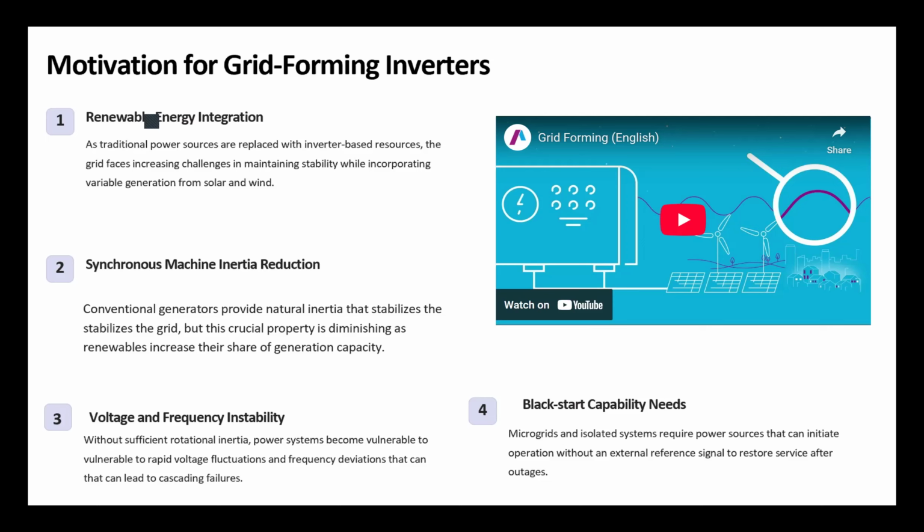Okay, we are going to need time for transitioning from one state to another when we have a mechanical system. On the other hand, in inverters, we don't have that delay. When you change the setting of the inverter's control system, the output changes instantly. So any kind of variation at the output, at the terminal, any errors that are input to that PID controller or that PLL synchronization system, instantly get an answer and it would affect the output.